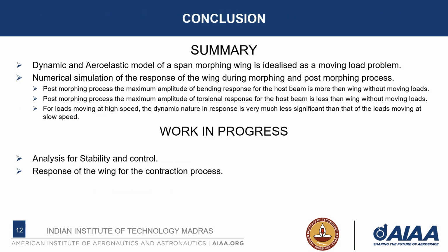Now to summarize our work, first we have developed a dynamic and aeroelastic model of a span morphing wing based on the idea of a moving load problem. Then we have numerically simulated the response of the wing during the morphing and post-morphing process. We have also seen that the aeroelastic response is always lesser than the dynamic response of the host beam. This is just because of aerodynamic damping.